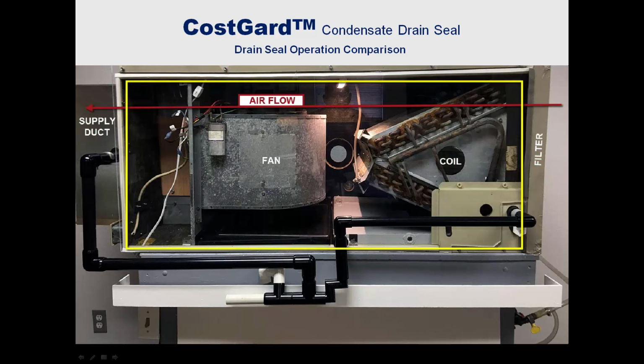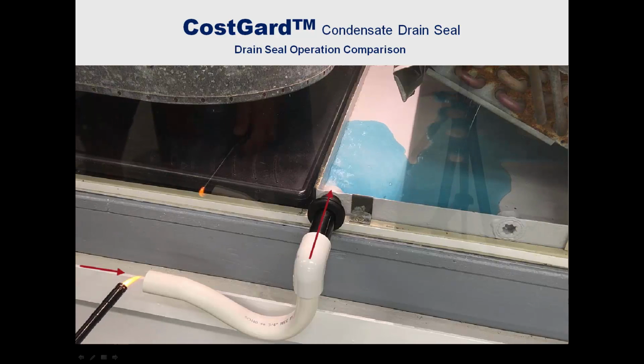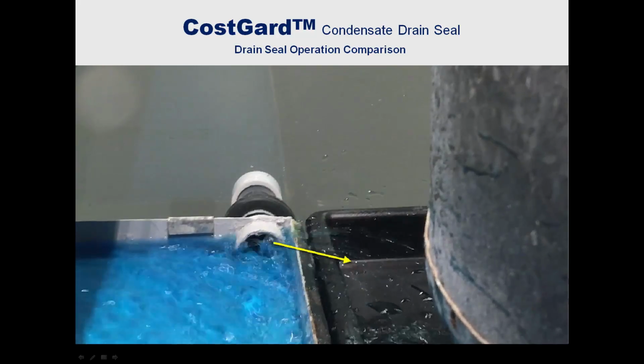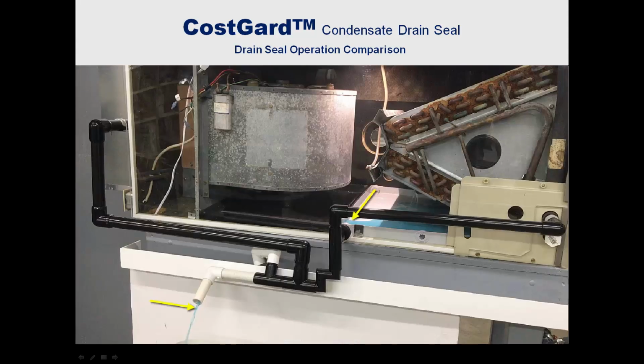With the aid of front and rear transparent panels, the effectiveness of the CostGard condensate drain seal system in preventing the blowing of condensate in a small fan coil unit operating at negative 0.6 inches of water column versus a trap is shown here. See the ingestion of air through the empty trap as the drain pan fills, and the blowing of condensate from the drain port back into the unit. Now, with the CostGard condensate drain seal system, note that there is no condensate blowing, and condensate flows smoothly through the device.